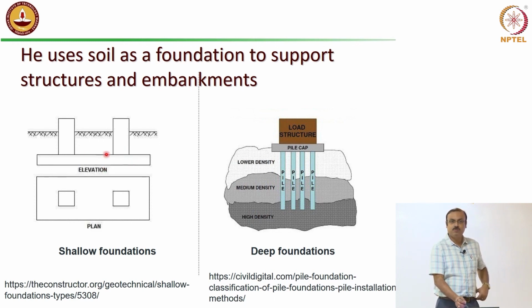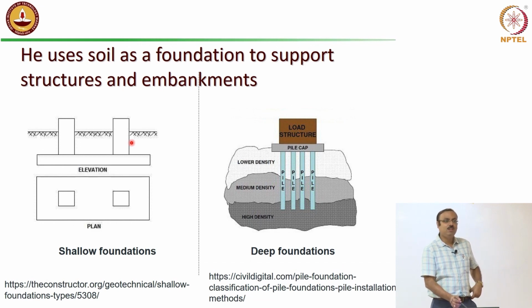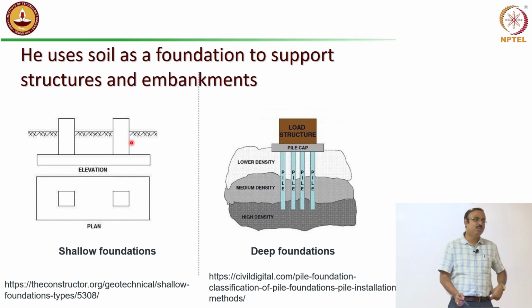In fact, I would always prefer this because the cost is less, and construction and problems are less. But there is a but here. The but is that the soil surrounding this should be good enough to take that load, isn't it? See, ultimately, what is the purpose of a foundation? Foundation is transferring the load. Whatever load is coming from the superstructure via this structural element, it is transferring to the adjacent soil. Now, if the adjacent soil is very weak, what does it mean? It will not be able to take the load.